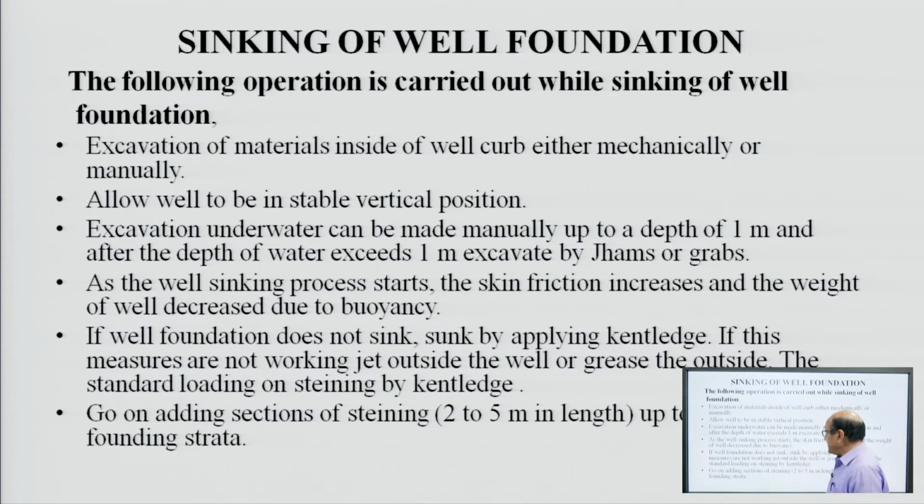If the well foundation does not sink, it is sunk by applying kentledge. If the measures are not working, jet outside of the well and grease the outer side of the well, so that the skin friction may reduce.